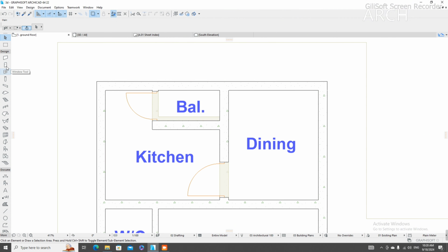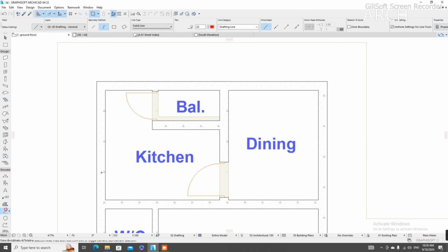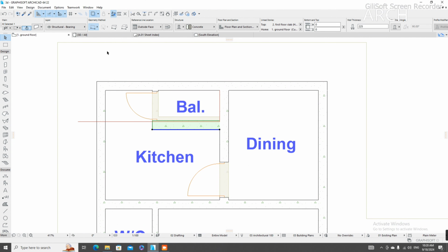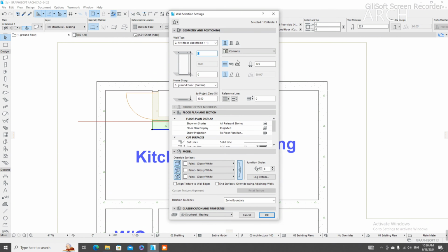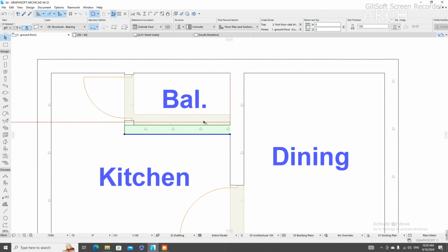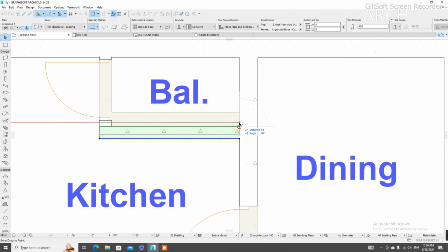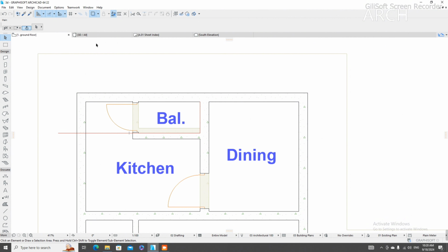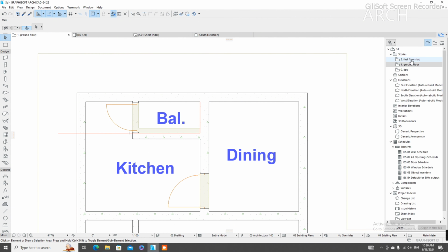Okay, perfect. Which means we have to increase this wall for the door to match. So if we do that, we have to go back to our DPC level. Let's check what we have here. Let's just change this wall to 800mm. If we are done with that, then let's go back to our wall tools and change this thickness to 150mm to help minimize our space. So we'll come back here, we'll take this to this. Okay, perfect. Let's go back to our ground floor, our DPC level.